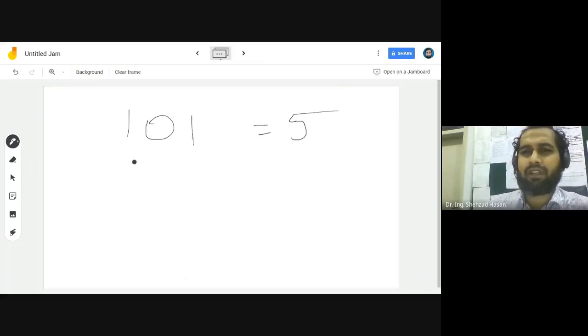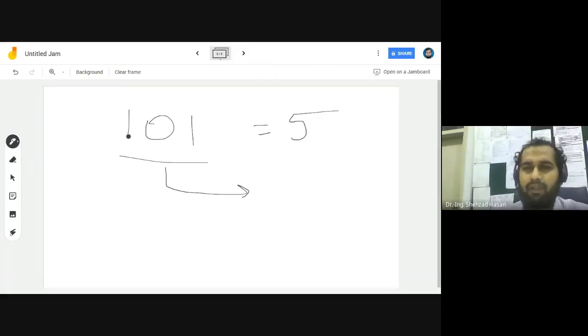But when you're talking about 101 as a signed number, that is not 5, because in signed numbers we treat the first bit as the sign, the bit having a negative weight. If it's a 1, it would be considered as -4, right?